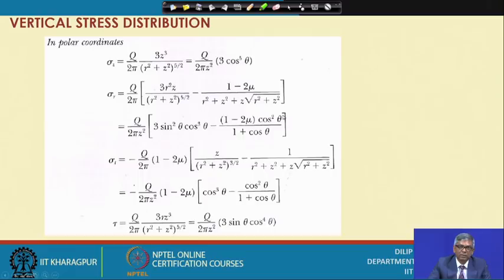Similarly, there is sigma r, that means the radial direction component, sigma t, the tangential component, and there is a tau. So, all those stress components are there, but generally we apply load vertically, and this vertical load always creates a significant, large value of vertical stress, and because of this vertical stress soil compression will take place.